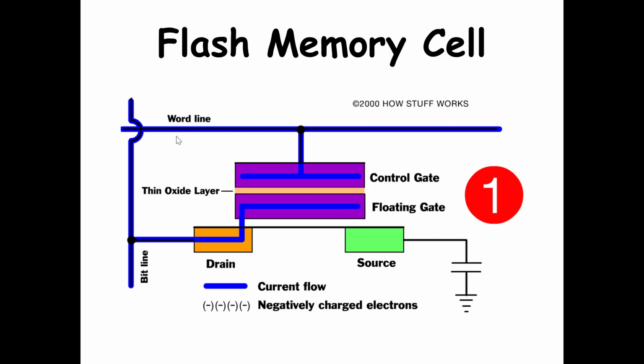So typically, when you have such transistors in a matrix, or what is known as an array, the control gate is enabled by a line known as the word line. Of course, this is for one bit, but you could have many such bits in a page. I stand corrected, they're not on one row, they're in separate rows with different word lines.